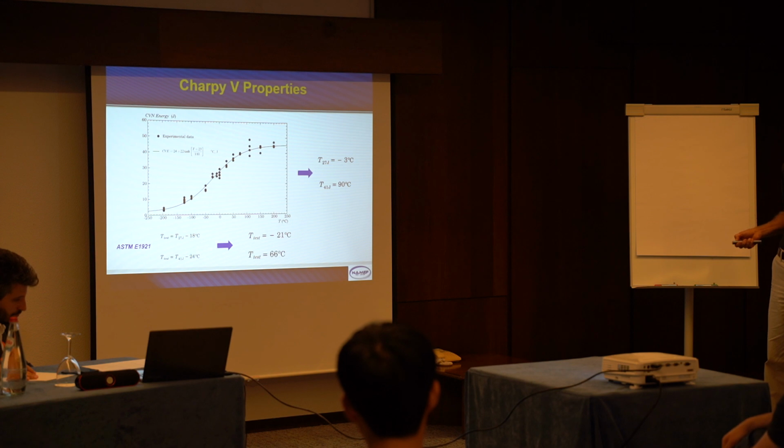So when we then employ what's in the standard, the standard will tell you to get your 27 joule temperature and subtract 18, then you get the test temperature, minus 21. If you use the 41 joules as your parameter, then you get a recommended temperature of 66. Okay.